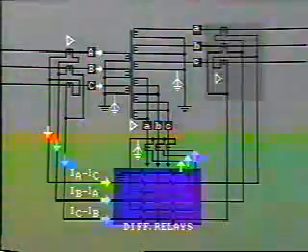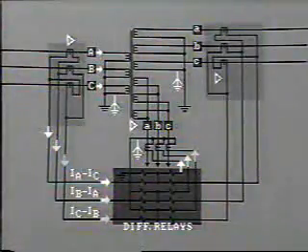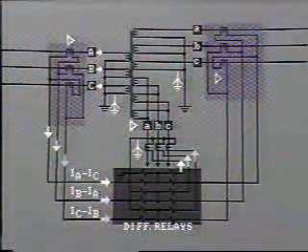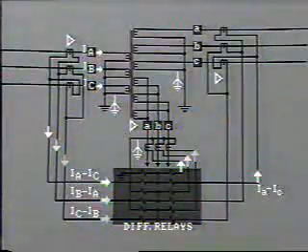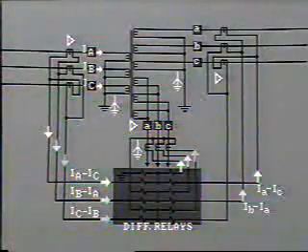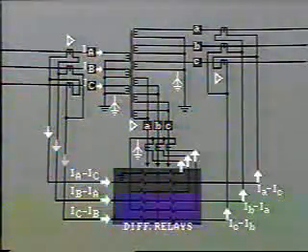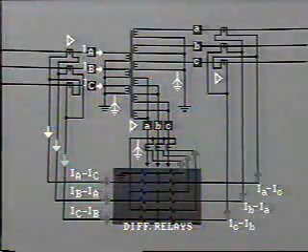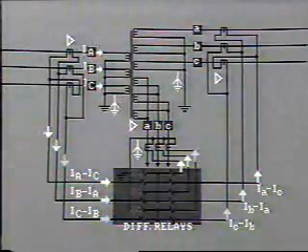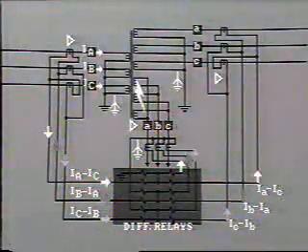Now, having checked the primary and tertiary windings, let's check the phasing of the CTs in the transformer's secondary. These are delta connected like the primary. Hence, like the primary, the currents from the relay are IA minus IC, IB minus IA, and IC minus IB. With balanced operating conditions, these three sets of currents cancel, and no current will flow through the operating coil.